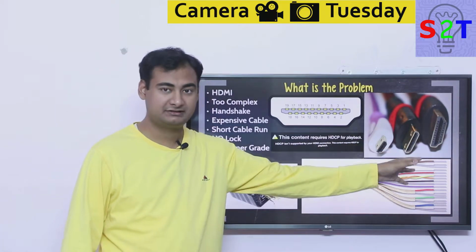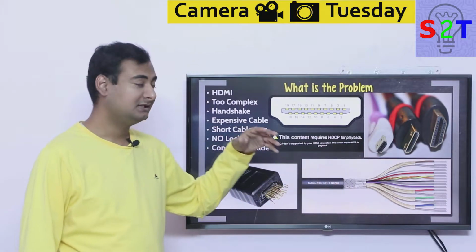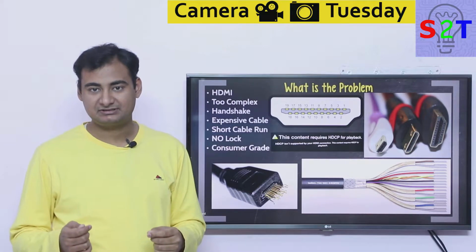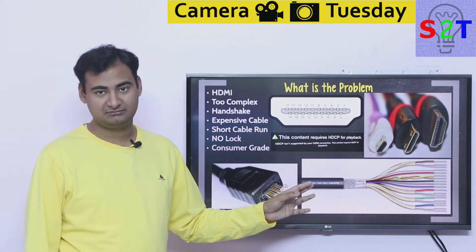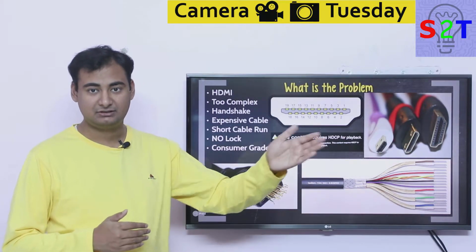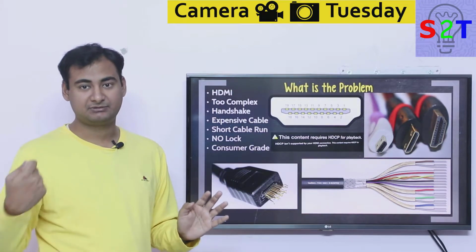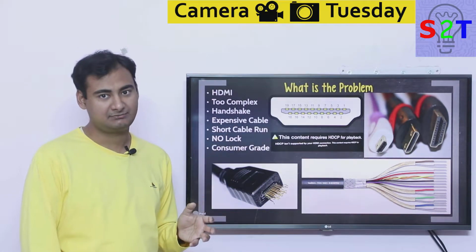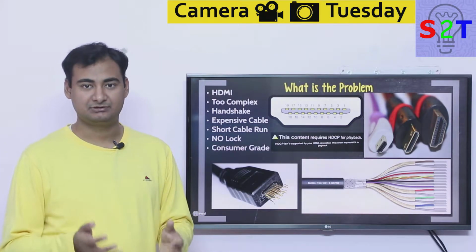Even though we have three interfaces, full HDMI, mini HDMI and micro HDMI, the fact that it requires 19 cables, like if you think Ethernet cables are complex, try opening these up. So these have 19 independent cables running through it. It's very complex. It does not run for very long distances and does not have a locking mechanism. So basically it can be pulled out even with a minor snag. And on top of that, it is a consumer grade product, so it has a lot of copyright protection but does not have many other things that people would want.